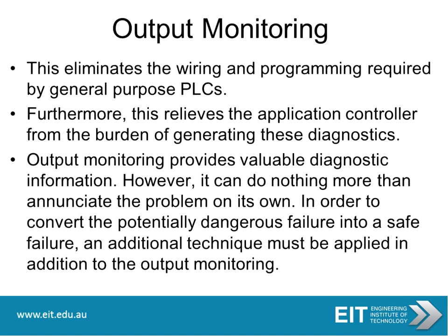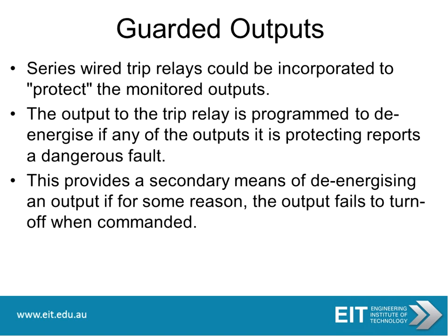Now this eliminates the wiring and programming required by general purpose PLCs. It also relieves the application controller from the burden of generating these diagnostics. So this output monitoring provides valuable diagnostic information. However, it can do nothing more than enunciate the problem on its own. So in order to convert these potentially dangerous failures into a safe failure, an additional technique must be applied in addition to the output monitoring, and that we call guarded outputs.